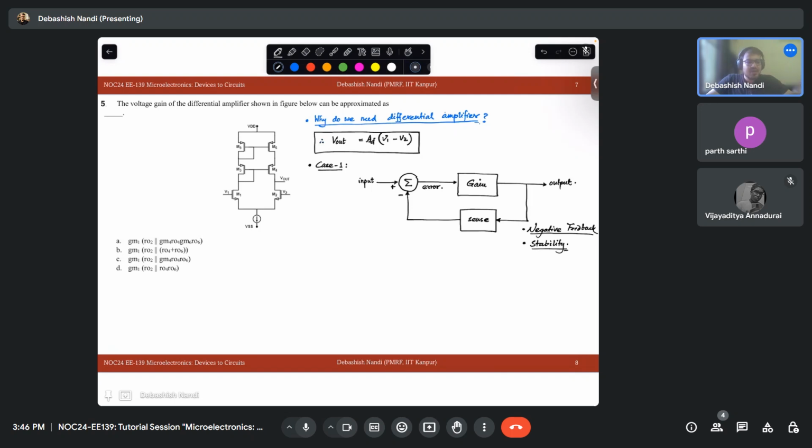Then your eyes will act as a, and the speedometer will act as a sensor there, and it will show you that no, you are exceeding the limit. Then you will just slow down the acceleration. Then it will come down to 38, then you will again put it to 41, then maybe 39, and in that sense you come to a speed so that you maintain the 40 kilometer per hour mark. So this sense of feeding you back by the speedometer through your eyes is called negative feedback. That gives you the stability, in the sense that you maintain your desired output at 40 kmph.